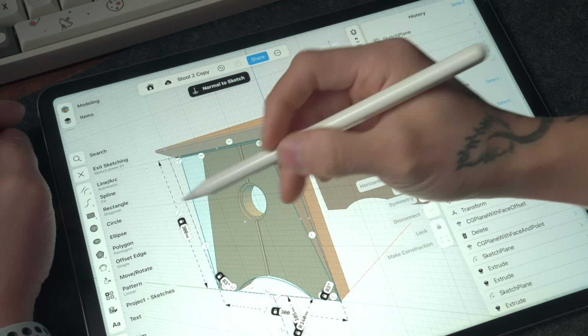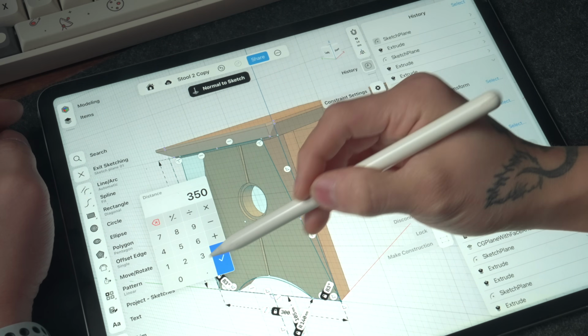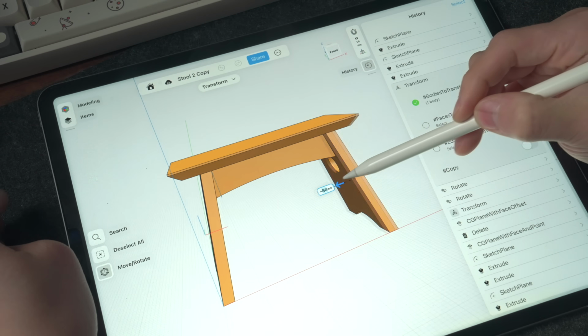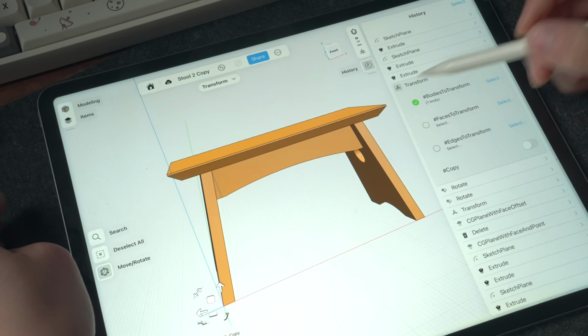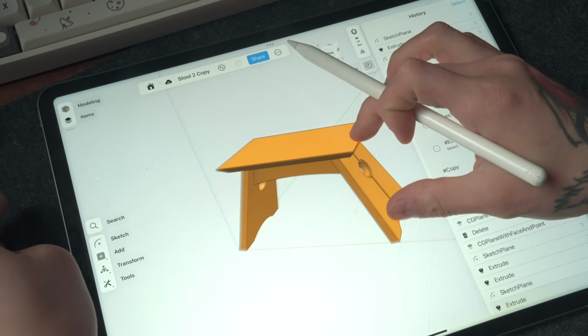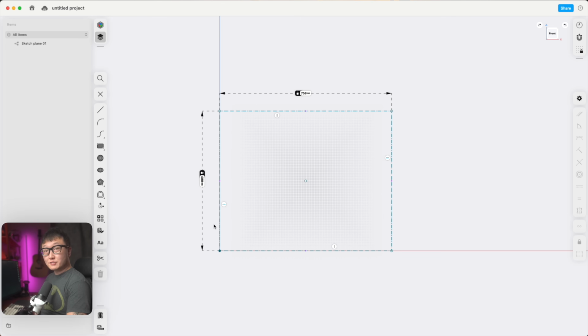And that's because in parametric modeling, our sketches are not directly connected to the 3D bodies that we're going to extrude later on. And those 3D bodies are then connected to other sketches and other bodies. So if one sketch isn't constrained properly and it gets messed up in an update, then everything that depends on that sketch is going to get messed up with it. So when we're dealing with parametric modeling, it is really important to get into this habit of properly constraining our sketches.